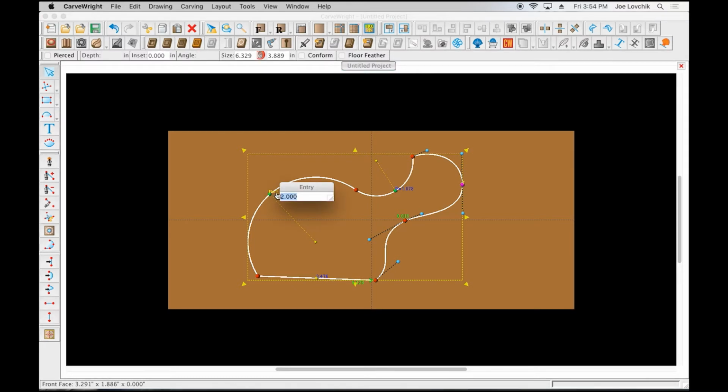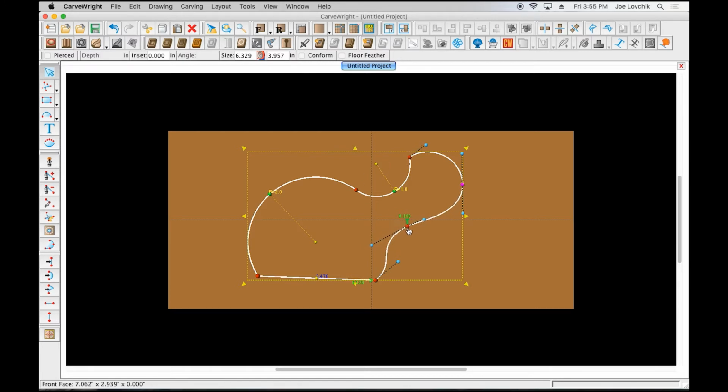and you'll see that it says R2. So it's coming from the center point of that arc and determining the radius, and we can input that there. So we can put constraints into every part of everything that we are designing here, including how far away they are from axis lines. This is an attach point, where this green arrow is pointing. This is how far it is from the center axis line on the horizon here.